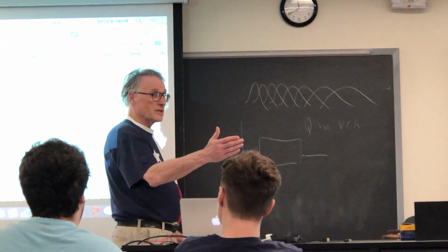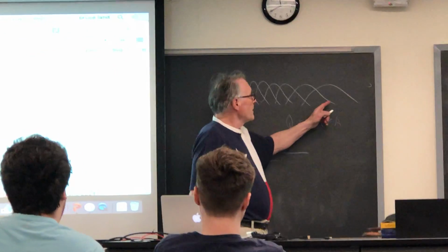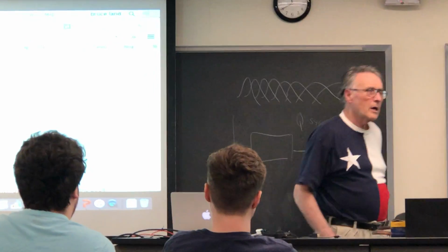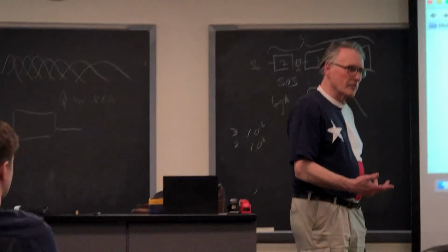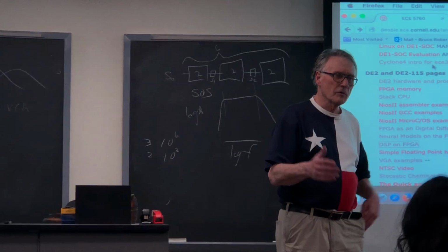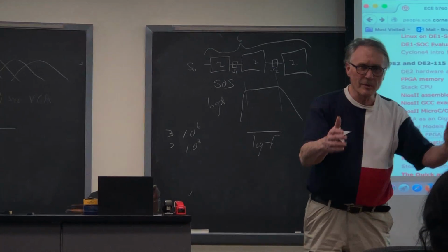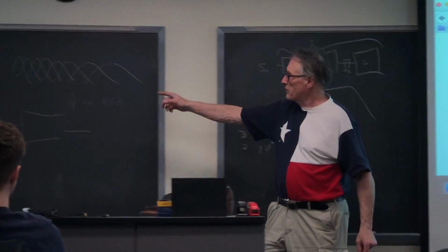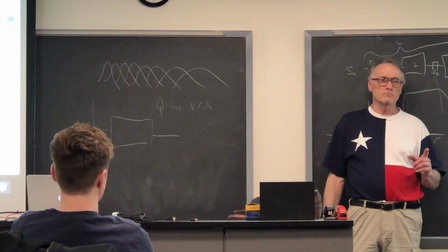So it's a constant fraction rather than a constant value. And that can make a really nice continuous time filter frequency analyzer, because you don't have to segment the data and then FFT that segment and then segment the next data. You generate a new value of the filter output for every audio cycle in parallel.